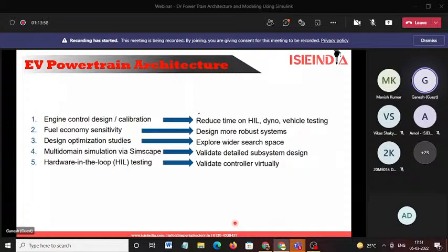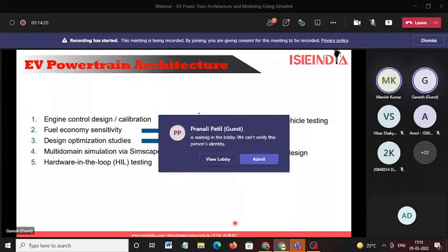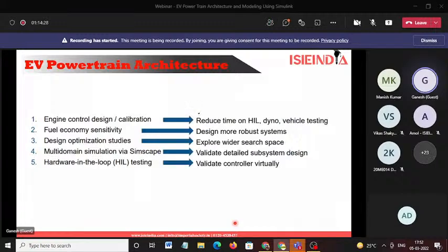Many of you know the Indian drive cycles, so we have different standards. What is the IDC? They take a certain road as an input reference, with some potholes and so on. They take that IDC cycle graph, which I can show you in the next slide, give it as an input, and run the motor for a few thousand kilometers. Based on that, we will know the performance of the motor.